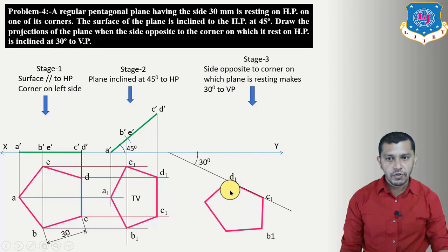So this will be our top view again, and we have to give the numbering like this: C1 D1. Here we will get B1, here we will get A1, and here we will get E1. So this is our top view. These both figures will remain the same because we have to copy this figure over here, but just inclining the C1 D1 at an angle of 30 degree. And right now this 30 degree angle is phi and beta both, because true length of CD is equal to the plan length of the CD, and we have to always copy the plan over here.